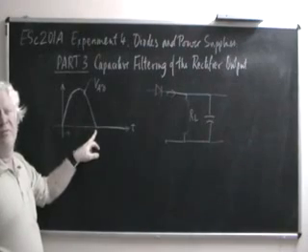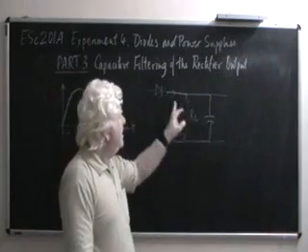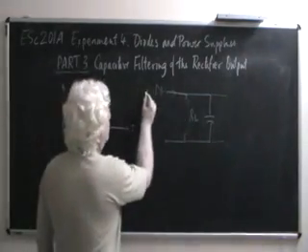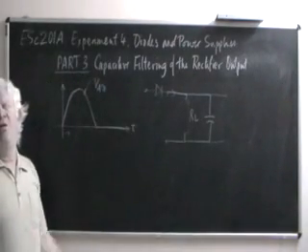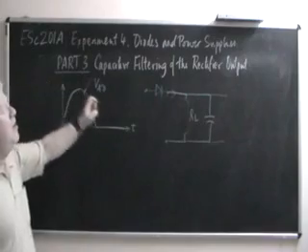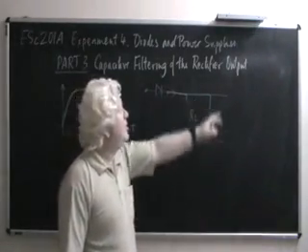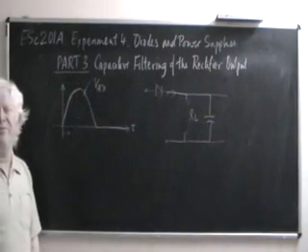the sinusoid. But because of this capacitor, this diode is now faced with a falling voltage on the rear end. On the anode end, the voltage is now falling, but on the cathode end of the diode, the voltage is fixed at the peak value that it just crossed.